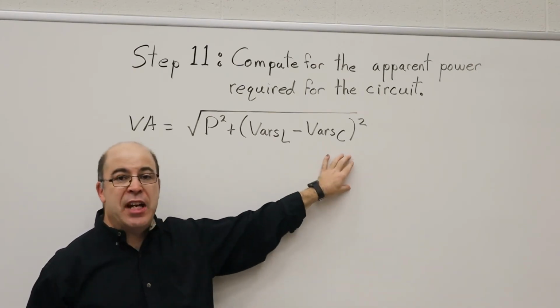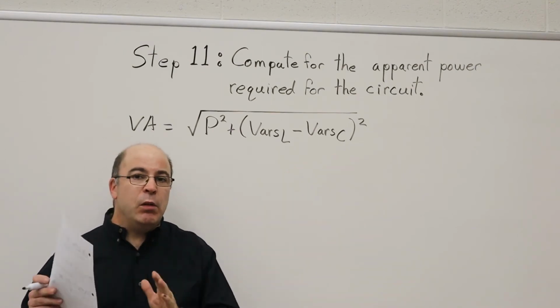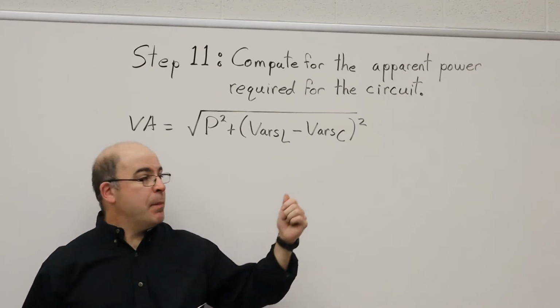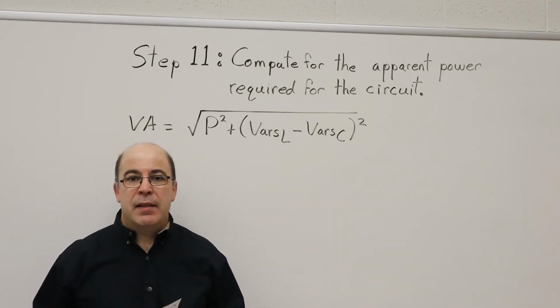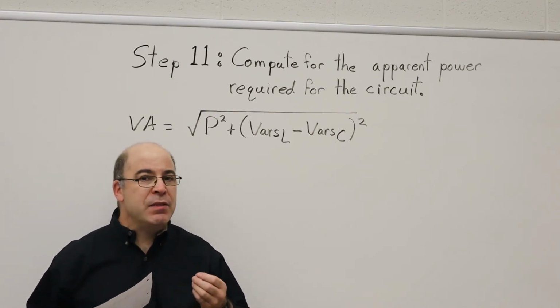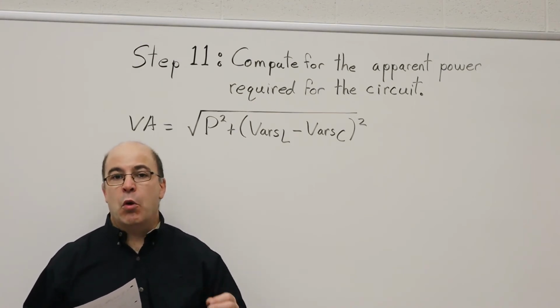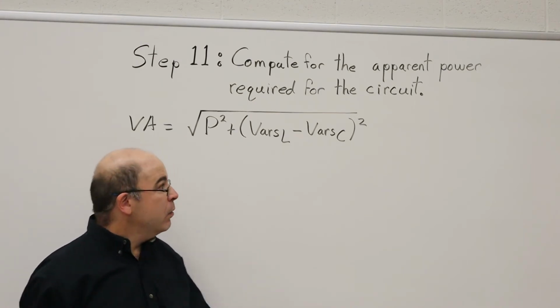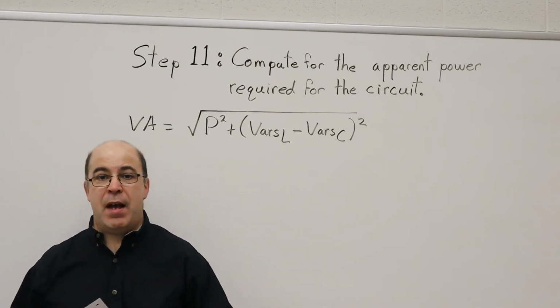The capacitors generate reactive power, inductors absorb it. And if we can closely match the amount of capacitance to the amount of inductance, the overall effect is I'm going to improve the power factor of my circuit, meaning my circuit is going to be more efficient. That's the ultimate goal that we're working towards. Now, enough about that. Let's proceed to start inputting our values.